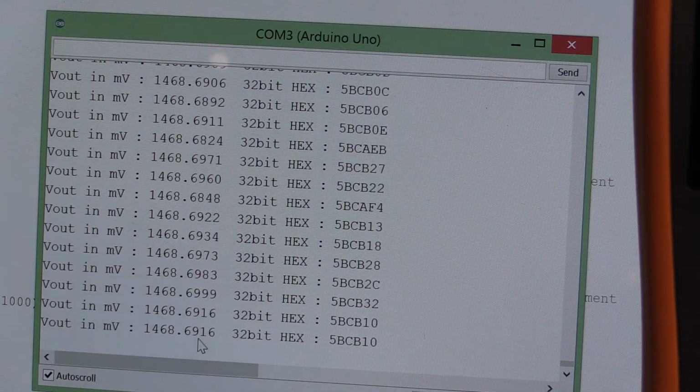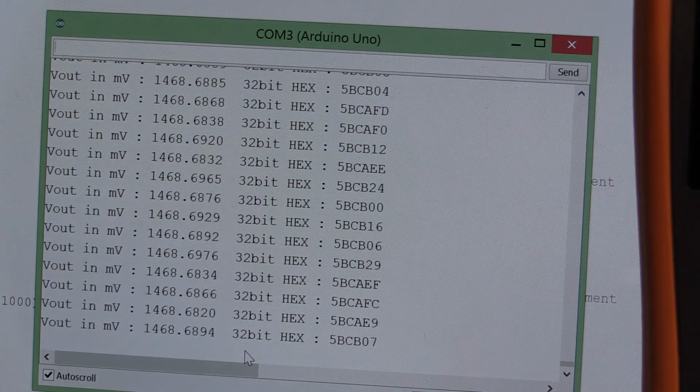So like a 24-bit ADC, you can see here that even though I have the resolution to go down to sort of nanovolts, it's not really very effective. It's jumping around quite a bit, and really only having down to 10 microvolts would probably be more than enough, or even just millivolts and maybe 0.1, 100 microvolts would be enough to control a power supply.